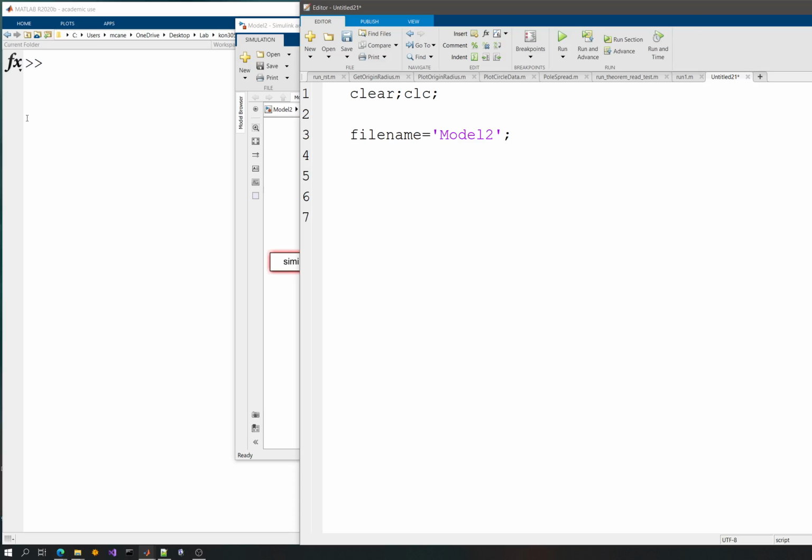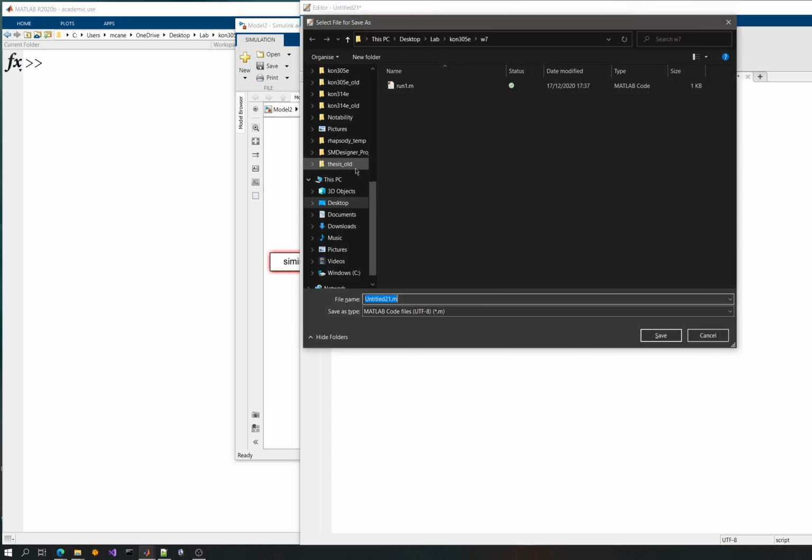Now before I start everything, I might want to create the data I want to use. So let's have a time of 10 seconds and a sampling time of 0.1. And let's have a reference signal here that is just ones, and I will use the size of t, and let's say run model.